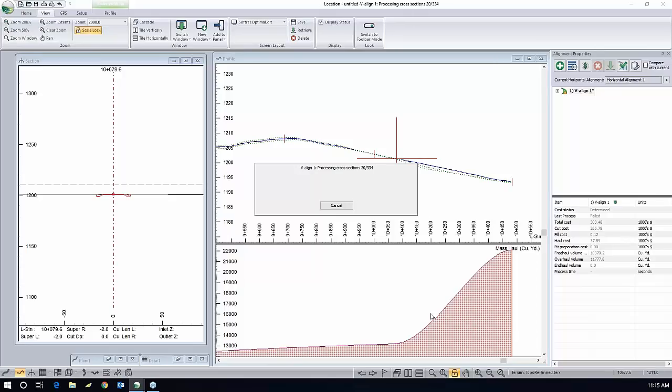So what the software is doing right now is it's trying to find the best vertical alignment that will give you the lowest cost. And hopefully it's balanced. It's finding it pretty quickly, and it's definitely a lower cost road than the original was. We're down to this gap right here. What this means is at worst case scenario, we are 0.02 away from optimal, and it should go down to nothing, and then it'll just stop.